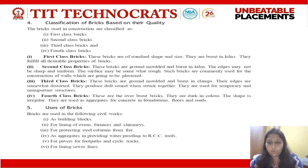Next, we have fourth class bricks. These are the overburnt bricks. They are dark in color. The shape is irregular. They are used as aggregates for concrete and foundations. As they are overburnt, they break up into pieces, hence cannot be used as block material. But yes, these pieces can be used as filler or aggregate material in the production of concrete or in the construction of foundations, floors or roads.